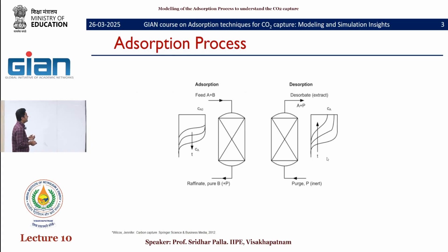Most of the A is adsorbed on the bed. Here we can see the mass transfer zone and how the concentration of gas molecule A changes with respect to time. As the process proceeds, the concentration of A at the exit increases. Once the bed is saturated, we observe the concentration of A at the exit. That is the breakthrough we discussed in our previous lectures.